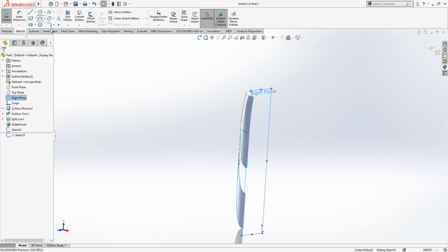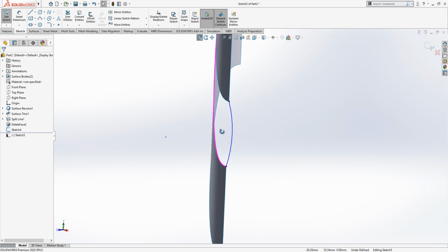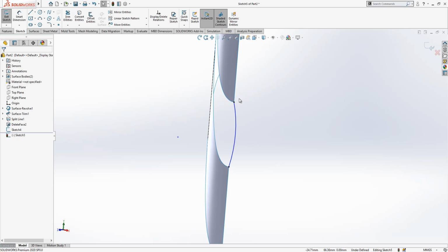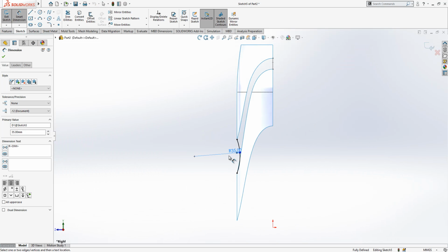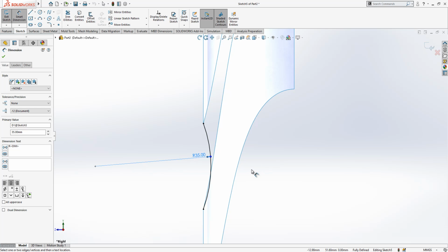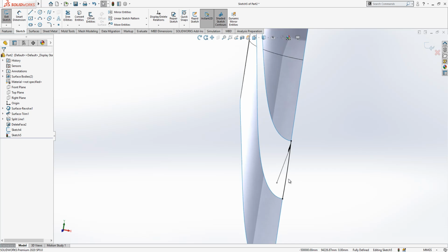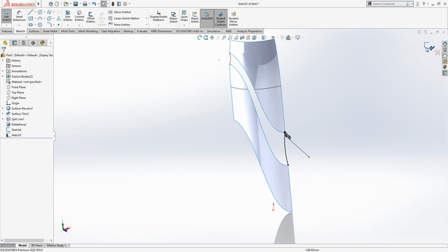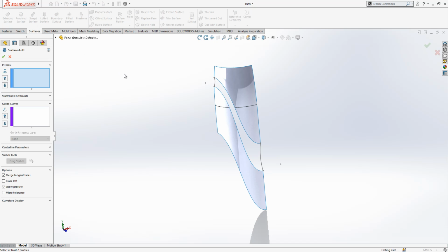So in the right plane, I create a new sketch. I select an arc here. So we define an arc with 2 constraint points, and here our value is missing. We will give it 35. If you want to look from normal, you will see something like this. Okay, this looks also fine. We close this, and then we go to loft.